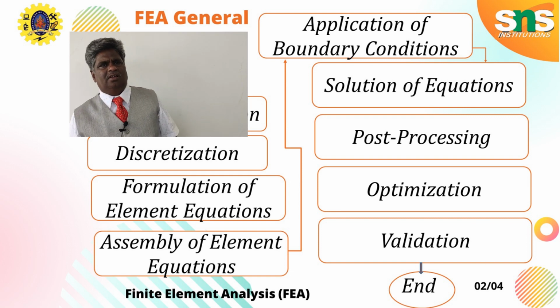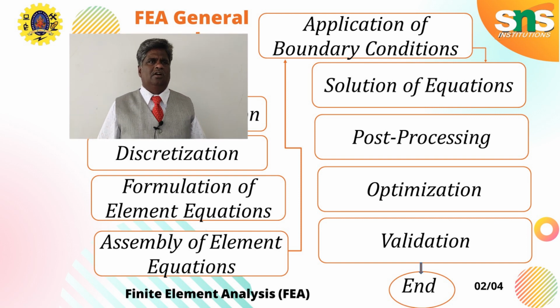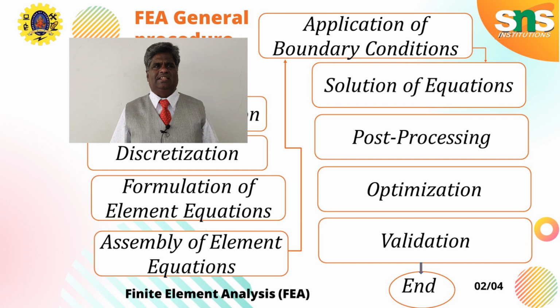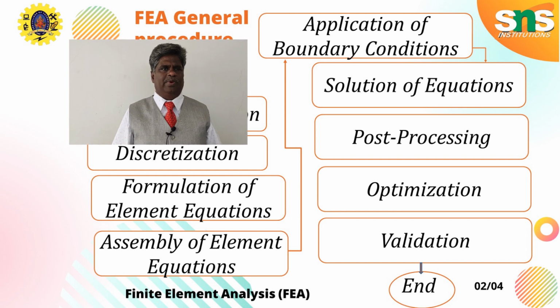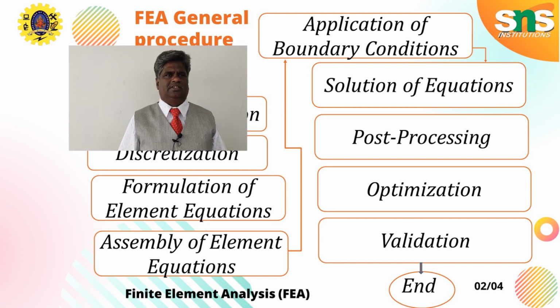Formulation of the element equation: the governing equations for each element are formulated using the principle of virtual work. This involves the selection of an appropriate displacement field, strain-displacement relation, and constitutive relation.